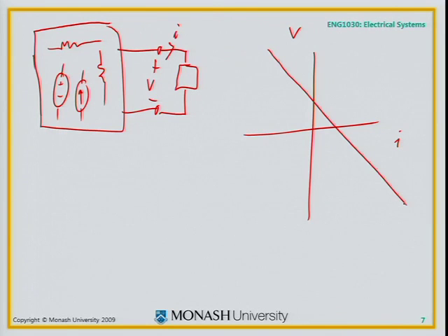But it doesn't matter what else is in there, or in what configuration. That's all I can produce. It has to be a straight line. So the most I can get out of it is a straight line that doesn't necessarily pass through the origin. Now how many measurements would I need to make? 2. Exactly. Now I don't necessarily know I'm passing through the origin. So in general I measure 2 VI points and the straight line between them and I'm done. I've fully characterised what must be inside that box.